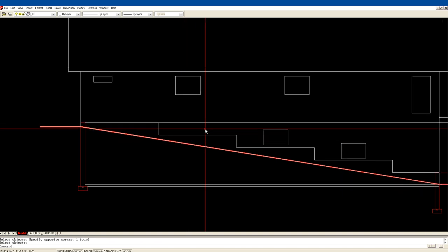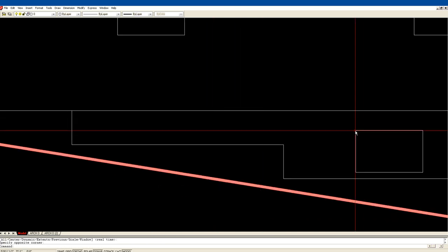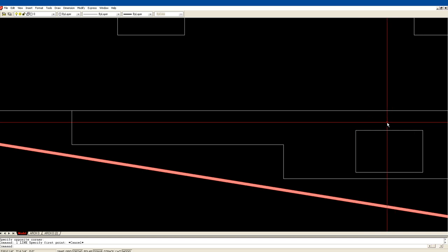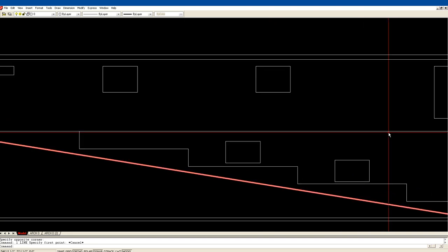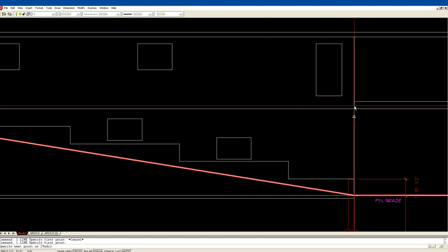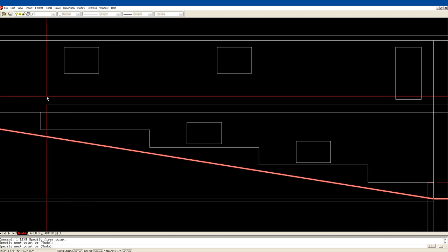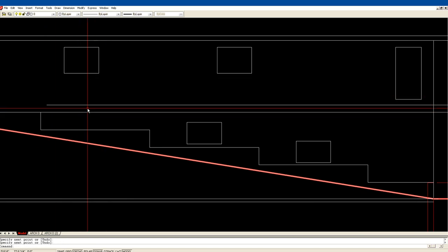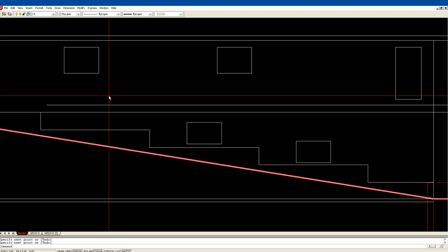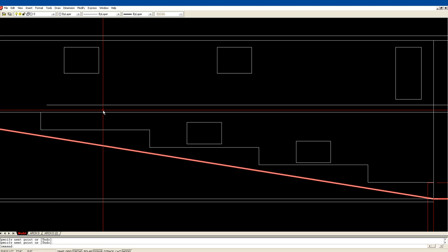Here up in this section, we still could sneak in a window. Let's say we had a bathroom in here. There's a couple ways we could do it. We know that this line right here would be the bottom of a beam underneath the floor, but what if they put the beam right into the floor? This is from the top of the floor. Let's say they put a beam in here. They would stretch it across. It'd be a couple of 2x10s, and then the floor joist would lock into that. So it would hold the floor joist and it would hold the beam.